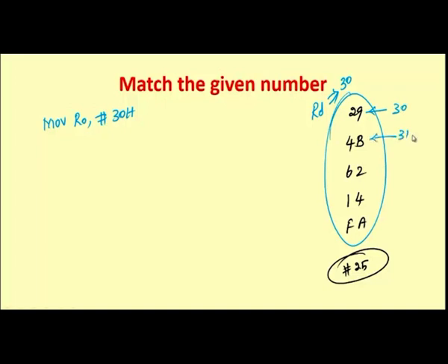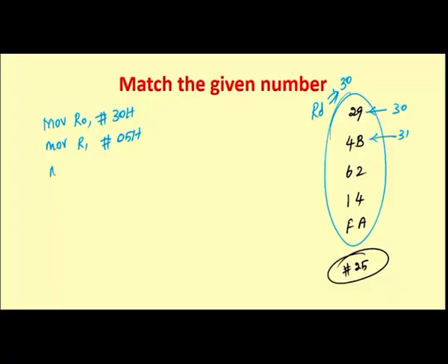So, how many numbers in your database will be initialized in R1? So, R1 comma 5 numbers, so I will give 05. So, the initialization process is over. Now, I want to compare it. For comparing I have to move to the accumulator, right. So, MOV A, @R0, the first data at R0, which is actually 29, into the accumulator.